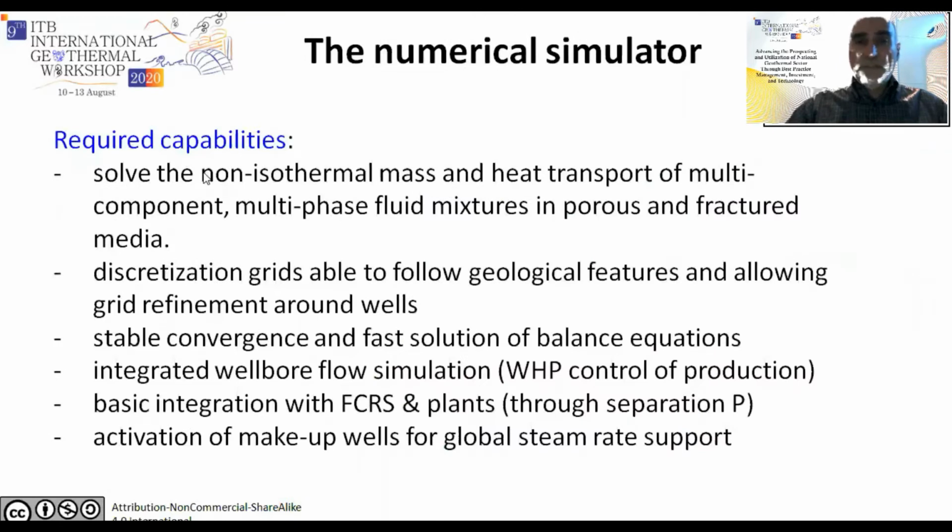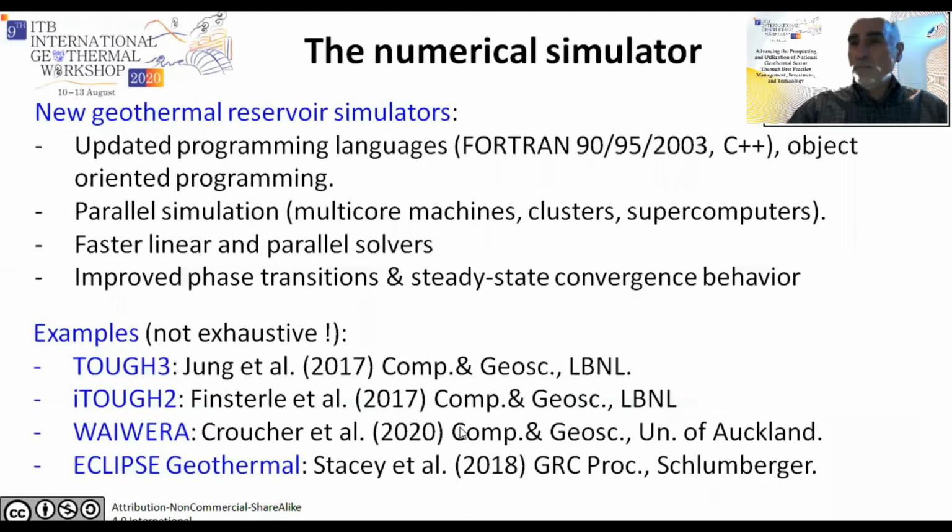So, the numerical simulator required capabilities. Of course, it has to solve the non-isothermal mass and heat transport of multi-component, multi-phase fluid mixtures in porous and fractured media. We would like to have a discretization grid able to follow geological features and allowing grid refinement around the wells. We would like to have stable convergence and fast solution of balance equations. Integrated wellbore flow simulation with wellhead pressure control, and a basic integration with a fluid collection and reinjection system and the plants, and the activation of makeup wells for global steam rate support.